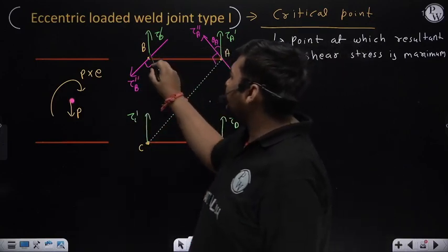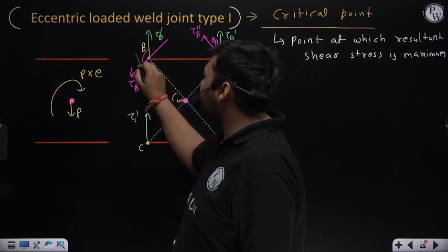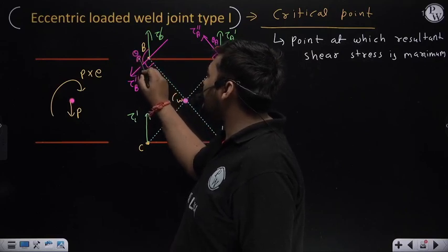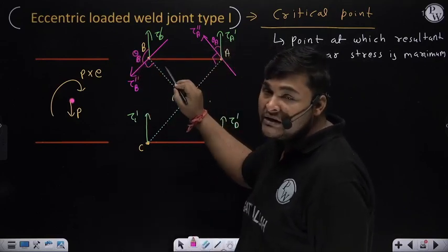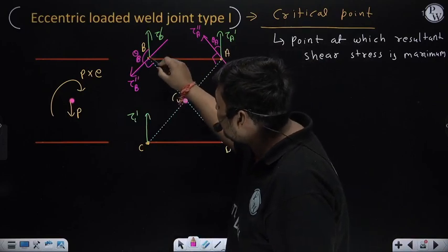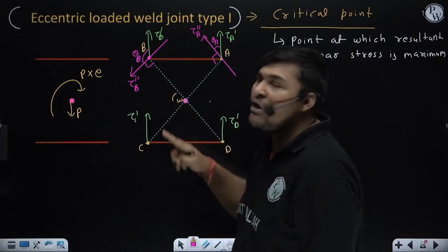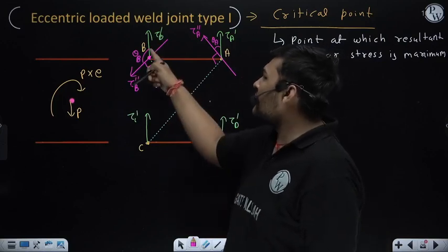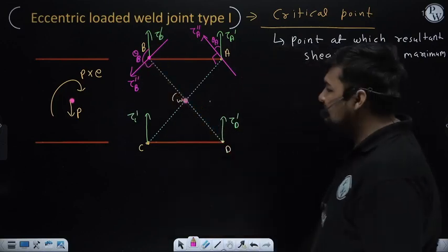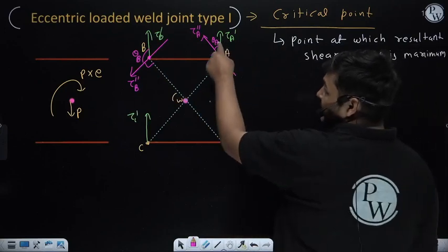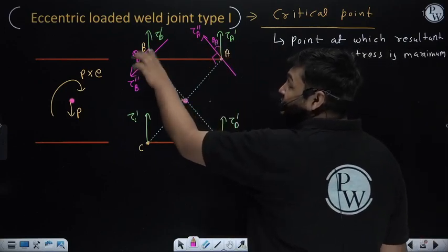Now the angle between the primary and secondary in this location is this. To locate this angle, first ensure that the tails of both vectors are coinciding with each other, and the vector arrow is in the outward direction. Then the smaller angle between these two vectors is the vector angle. Now you can see here theta A is less than 90 and theta B is more than 90.